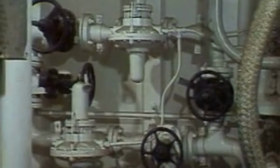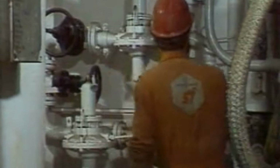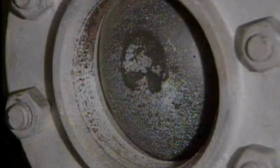Some people have been known to readjust the regulator in the air supply to increase the pressure, thinking they'll blow the plug out. They may blow the plug out, but they'll also blow the rupture disc out too. The rupture disc is this little device that ruptures when your operational pressure exceeds the rated pressure of the system.